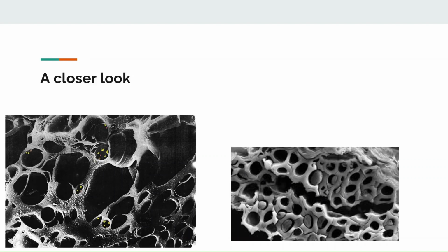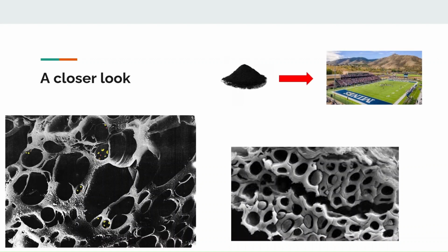One of the most important things about activated carbon is its surface area. Imagine a single gram of it having a surface area as big as several tennis courts. This happens because the activation process creates thousands of tiny holes or pores inside the carbon. These pores can give the carbon more space to trap unwanted materials. Just 2 or 3 grams of activated carbon can have the surface area of an entire football field, and that's why it works so well. The more surface area, the more places contaminants can stick.